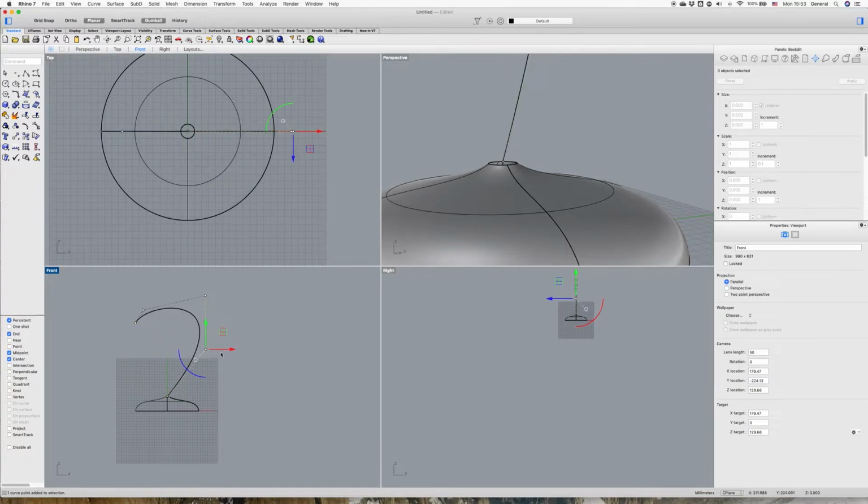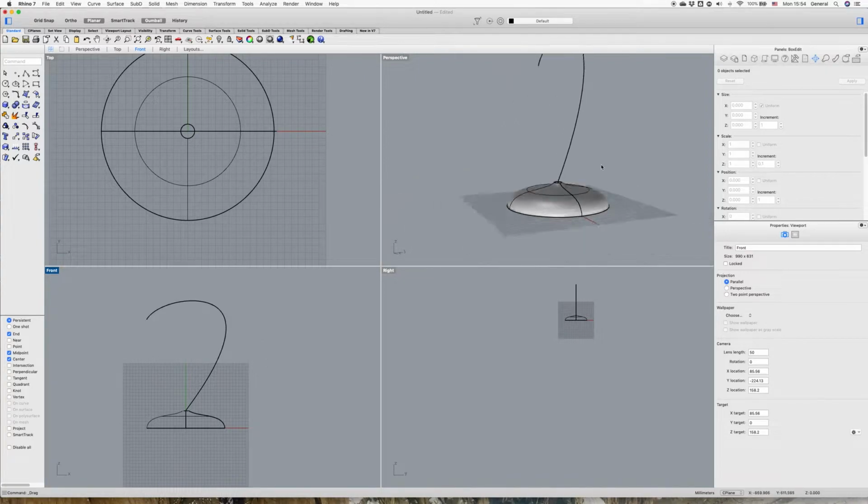And I have again my control points. Is this good? Yeah, it's good enough for demonstration purposes. So basically you want to revolve your 6 mm rod along here, or whatever spirals or curves you create. I want you to play around with that. And now you need to give the thickness to this curve. You want to sweep, which is the next.